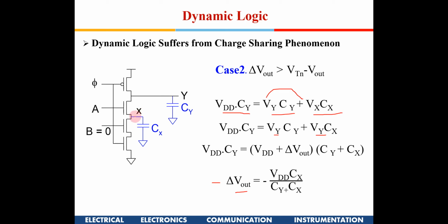Suppose initially this is VDD, and now some charge is coming here, so this voltage will keep coming up. So there is no adequate charge available for it to go to VDD minus VTN. That is the maximum, but it is still lesser than VDD minus VTN, because these two voltages become equal. After that no current can flow, right? So that is the condition which we have taken. Is it okay, Bera?